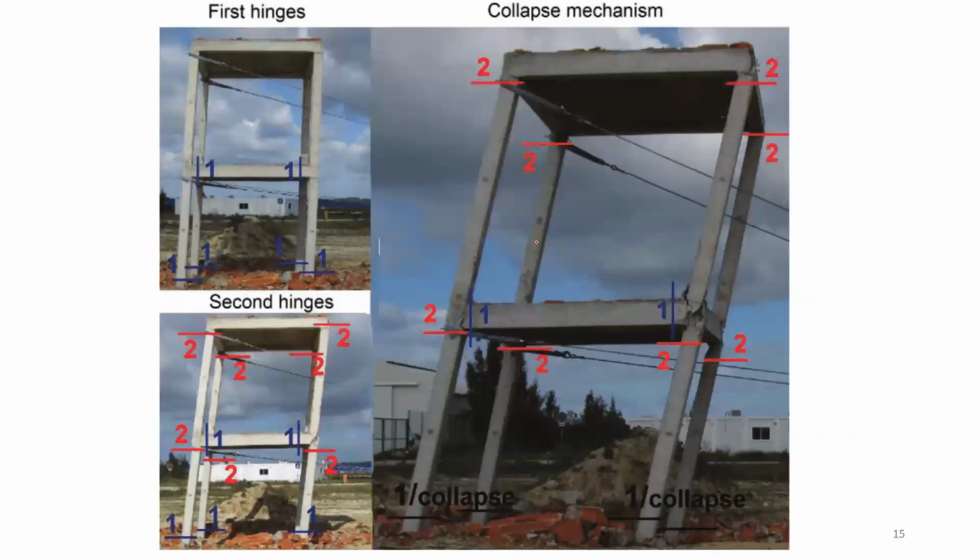See here, these are three real-time figures which talk about the plastic hinge formation. Initially there is a very small amount of deformation in the member, both in the top floor and the ground floor. This is the entire ground floor. Now, in figure one, they are applying a certain amount of transverse load, or it can be any kind of load.